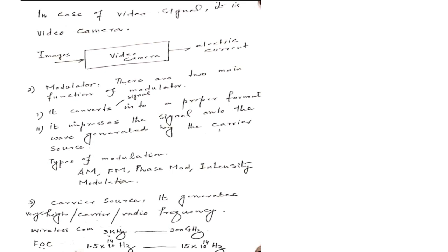In the digital communication system, we transmit bits in the form of ones and zeros, and the number of bits transmitted per second is known as data rate. So in order to generate the bits, the modulator needs to switch the carrier source on to generate 1, and it needs to switch off the carrier source to generate 0.